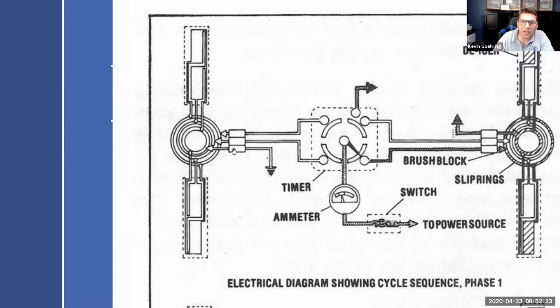And then this one right here, as you can see, is the ground wire, because you have to have a ground, otherwise you don't have a continuous path. So this would be heating element 1, heating element 2, and the return path from each heating element to ground. So we could say that heating element 1 heats up, was it this section up here? Heating element 2 is this one right here. And it's going to do the same thing over here.